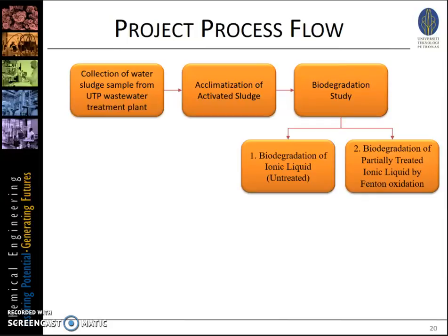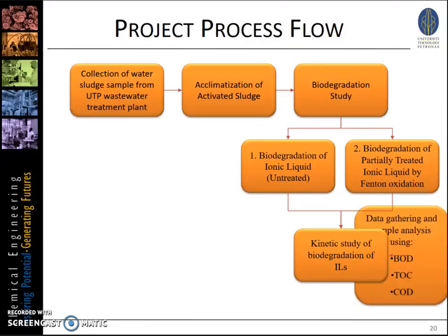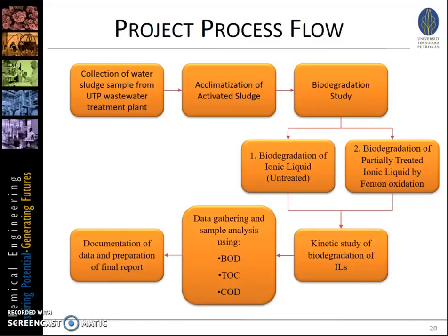which is biodegradation of untreated ionic liquid, and biodegradation of partially treated ionic liquid after Fenton oxidation. The results from both experiments are used for the kinetic study of the biodegradation of ionic liquid, and I will gather data and do sample analysis using BOD, TOC, and COD values, and finally I'll be conducting documentation of data and preparation of the final report.